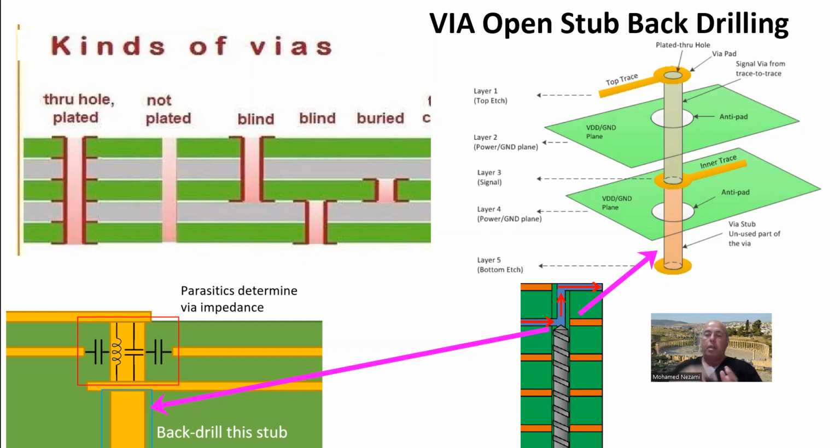So it will have the tangent or cotangent plot, where it's positive jX and then negative jX, and somewhere in the middle, when the stub length is exactly a quarter wavelength at that particular frequency, this will be a short. And when it's short, that's deadly, because all of the signal will reflect back out of phase with your signal, and you get a null. That's how we build notch filters in microstrip anyway.